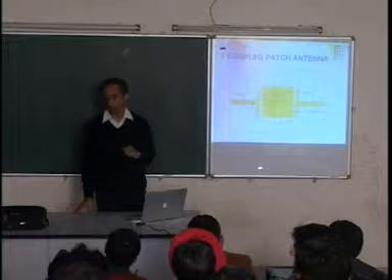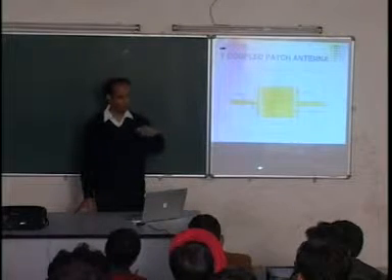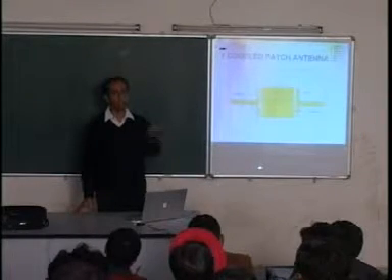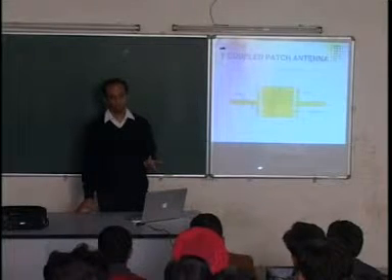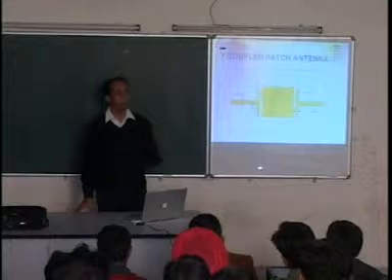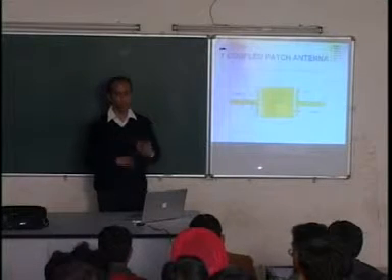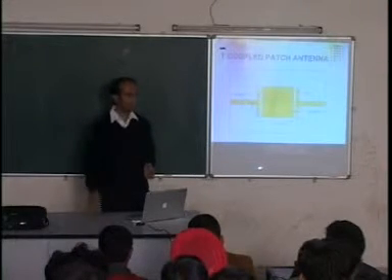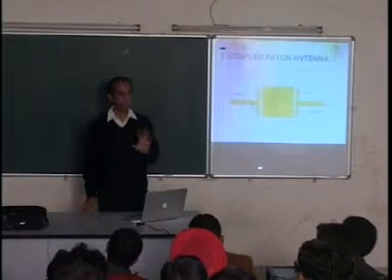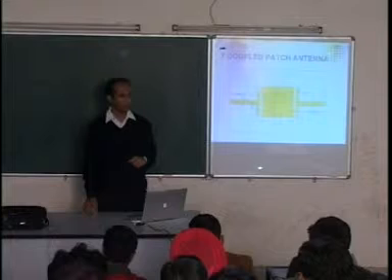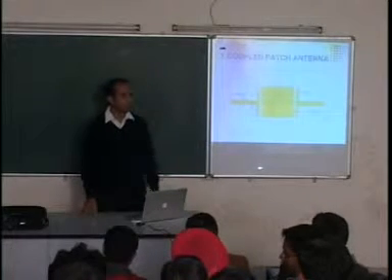It will not oscillate. If you transmit 90%, radiate only 10%, you are not using it very efficiently. The oscillator is generating a lot of power, only a little bit is going out. So it's a compromise. And nobody says 50-50 is the best compromise. It's just something we started with.